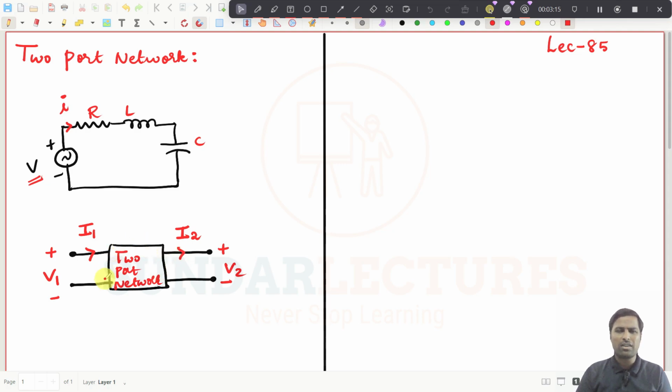That is I2. What is a two-port network? In this network, for an obvious reason, you should not have any source inside this network. That is the only condition. But you can have impedances, maybe inductive reactances, capacitive reactances, resistances, whatever it may be; we will commonly call them impedance values, right? For example, it may be like this.